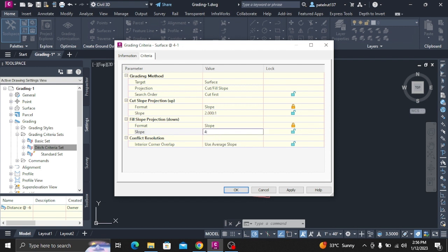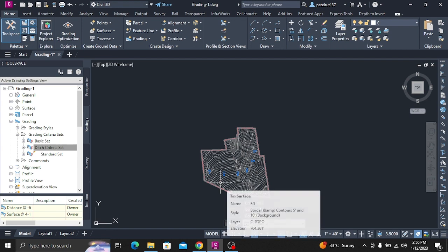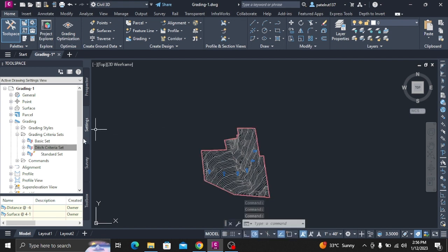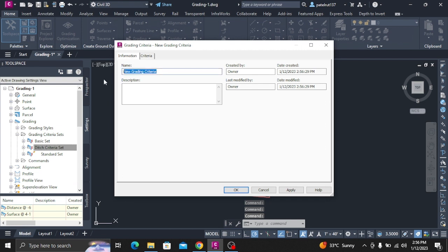Click OK. The new ditch slope pattern is selected for the ditch grading style. To view summary information about the style, click the Summary tab. Click OK. In Toolspace, on the Settings tab, the ditch grading style is added to the Grading Styles collection. The ditch slope pattern is added to the General Multipurpose Style Slope Pattern Styles collection.